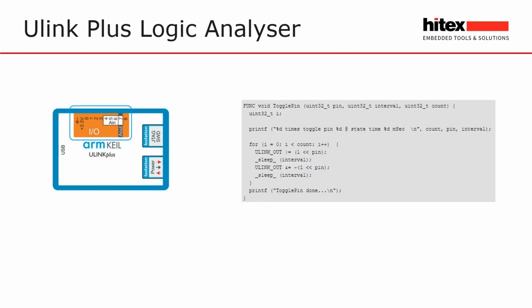There's an underlying scripting language, so we can talk to the various commands within the debugger, but those have been extended so that we can control the digital analog I/O as well. So we can read values, but we can also generate patterns down onto the hardware to do in-the-loop hardware testing.